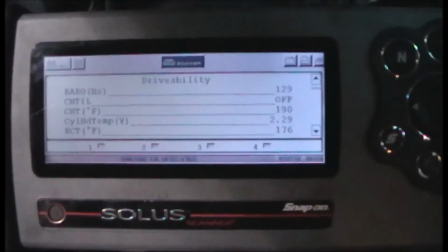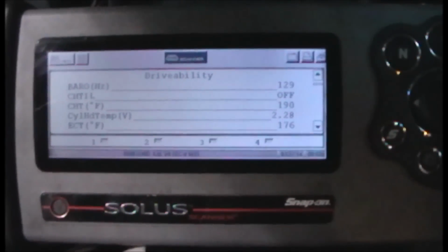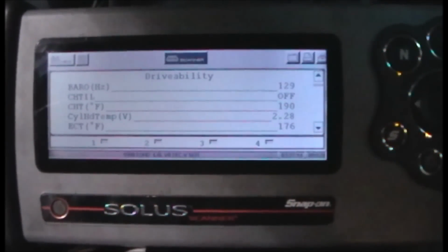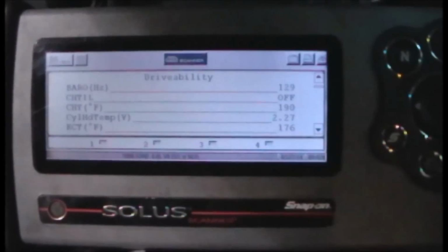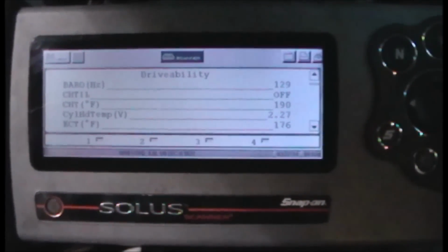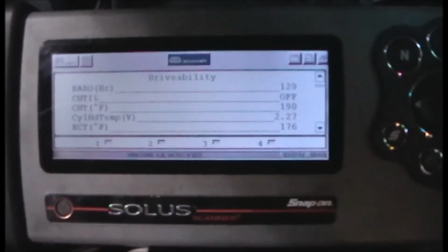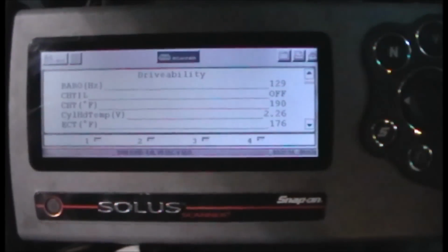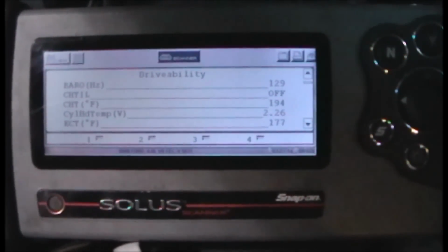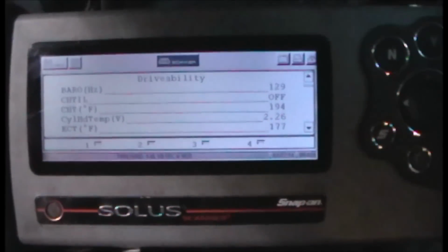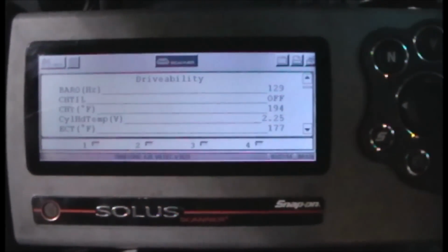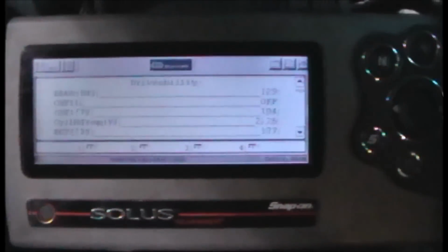So I'm in Pennsylvania. I'm maybe somewhere 800 to 1300 feet above sea level, and I should be seeing 147 to 156 in that range. So for me to be that low, I'm dealing with an unmetered air or incorrect airflow calculated. I have a chart for that.